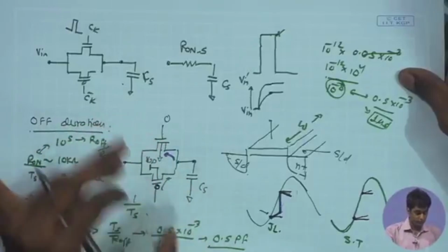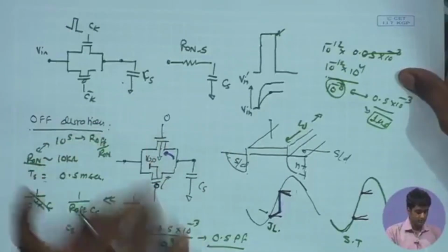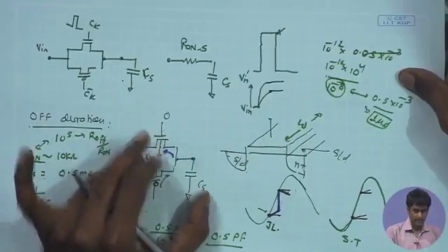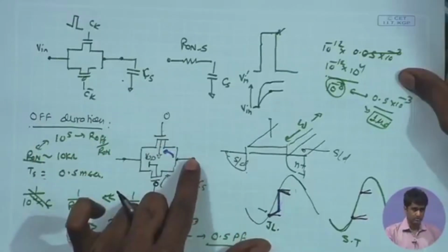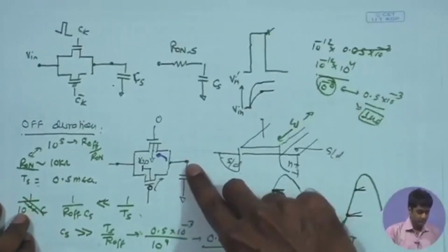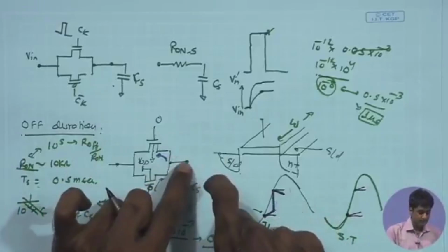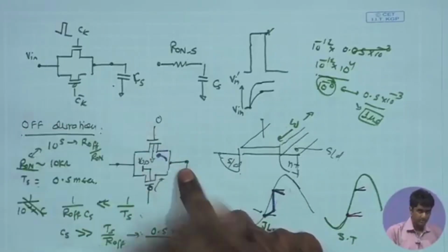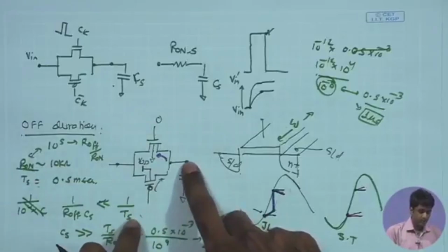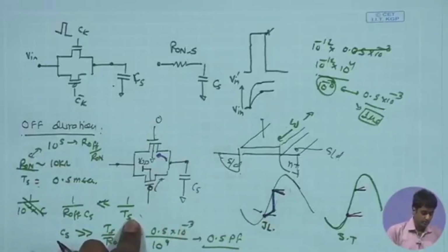Let us see those two contributors very briefly, and how they can have an impact on the sample data, how they can corrupt the sample data. Remember, the resolution that we are seeking is around 15 millivolts. So we do not want this signal to be corrupted by more than maybe a few millivolts if we want to preserve the signal integrity over here.